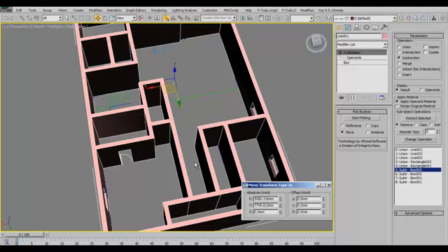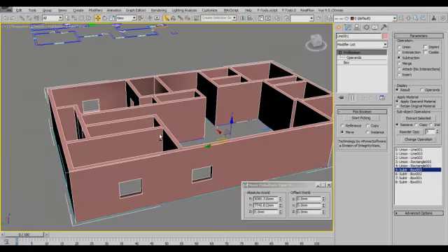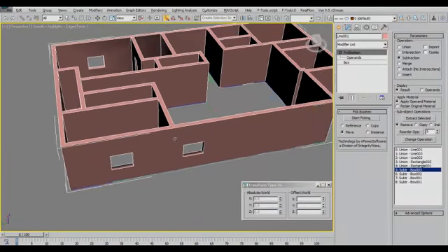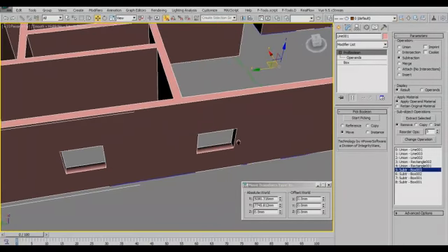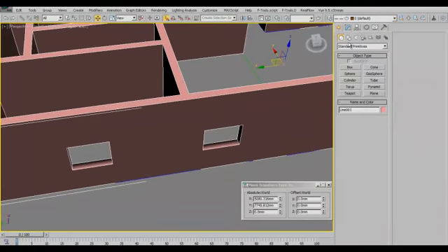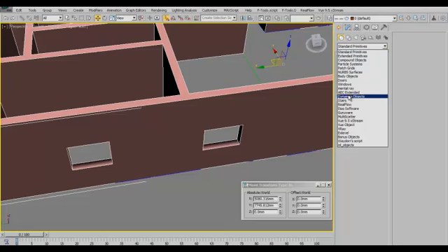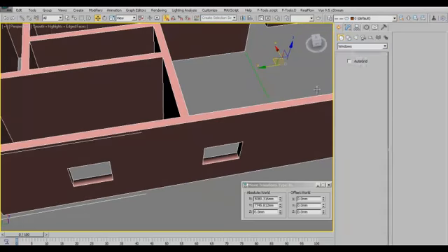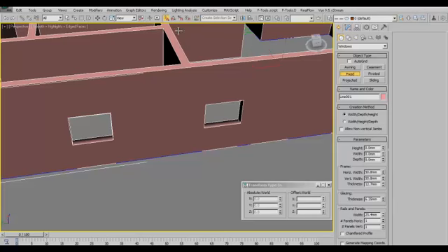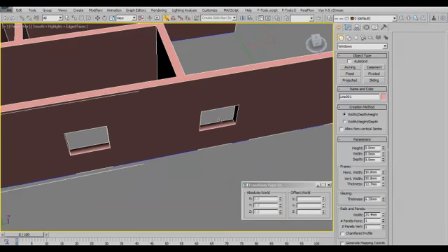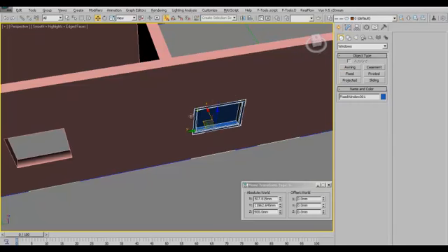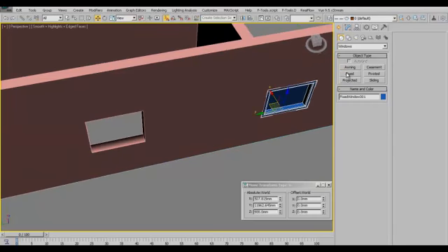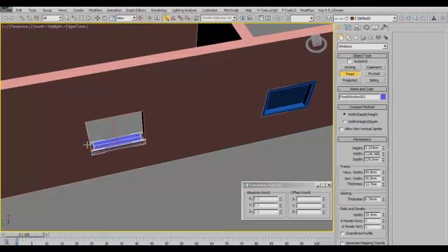So right now we'll see how we place our windows and doors into these openings, almost the same way as you place them while cutting through your AAC walls. And let's see how we do it. We go to Windows, then let's say a fixed window, and of course we turn on our 3-point snap, and we just snap to the spaces, and the same way there.